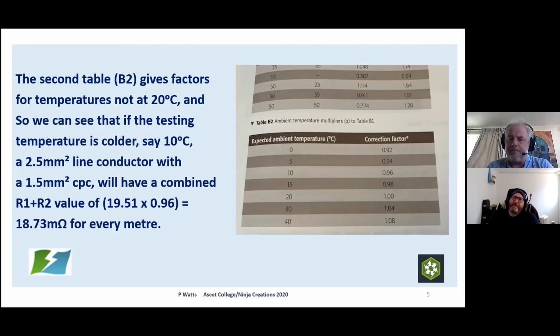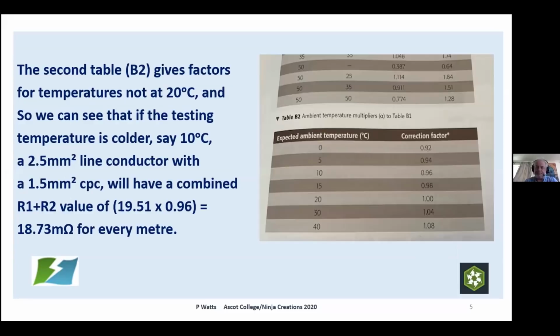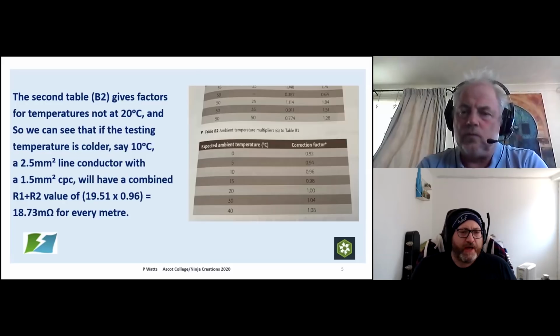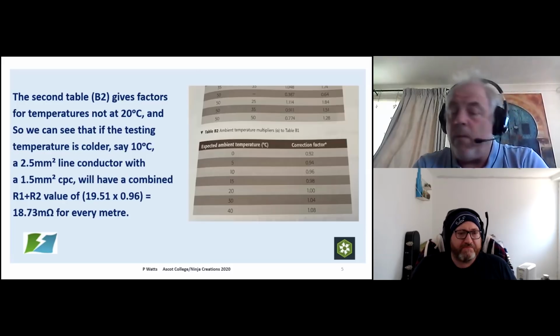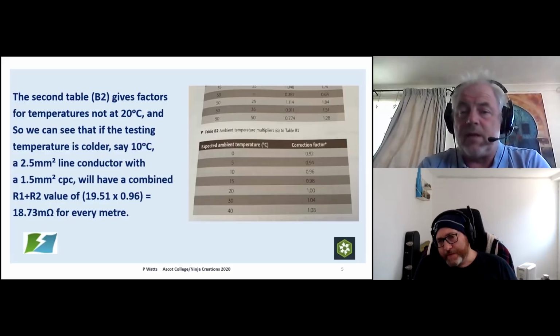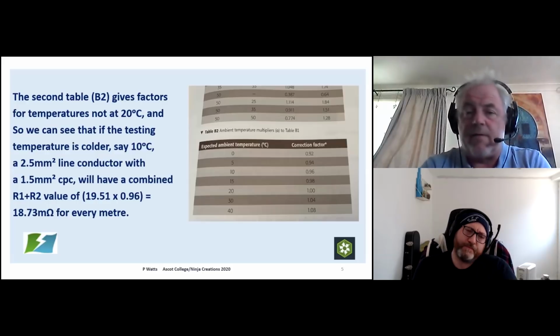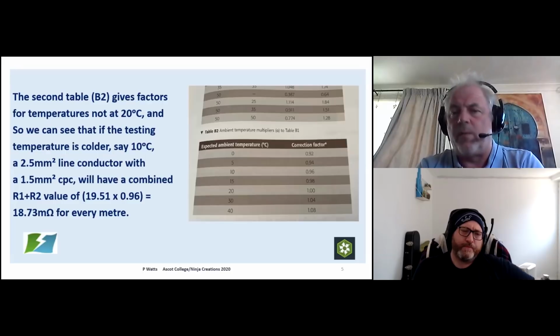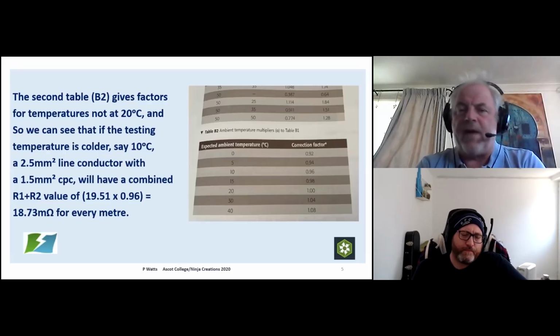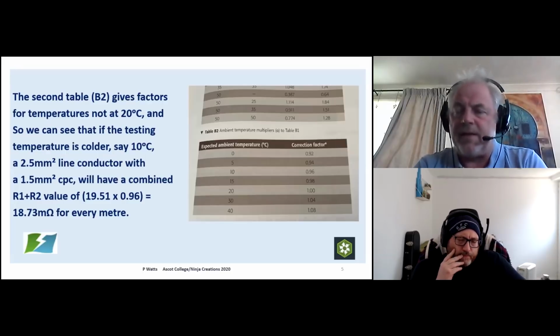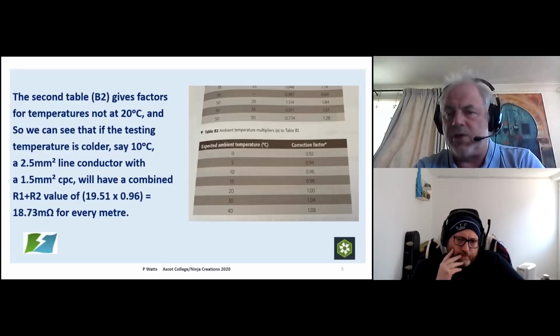Would it be best to just work out maybe the highest temperature as the worst case and make sure that you can work it out on a worst case scenario? If you work things out in the worst case scenario and then you find, hang on, there's a problem here, if you've got other factors that apply further down the system, which will actually reduce that issue, then you can take an engineering point of view and say, well, fair enough, I'll allow it because 80% of the circuit is at a much lower temperature.